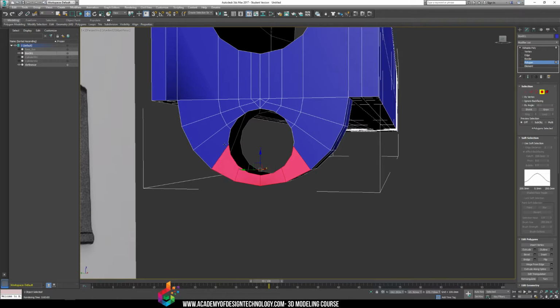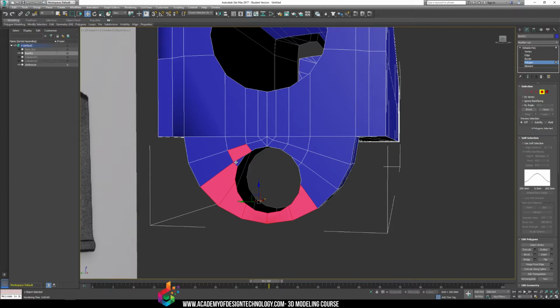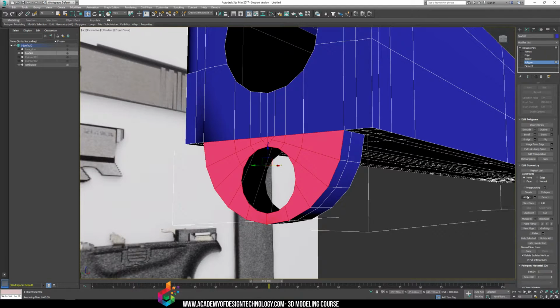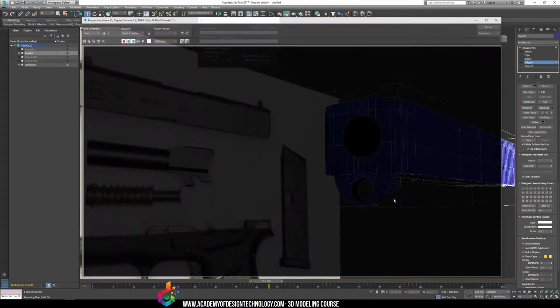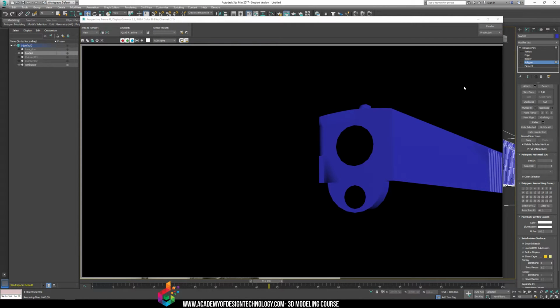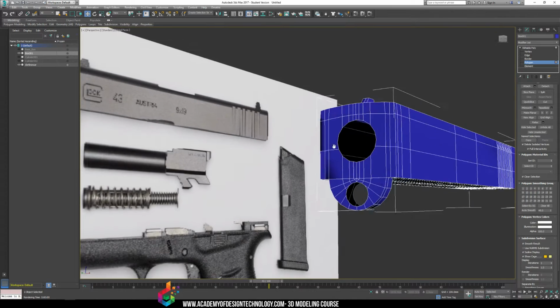So basically the front part of this gun at the very bottom here, I would actually change into one smoothing group for itself. So I'd grab this part of the gun, and this would be smoothing group. All should be one number. And right now I see that's actually 3 different numbers. But if I change this to 16, you can see that already looks way better down here. And I just need to keep going through my model and changing the smoothing groups.